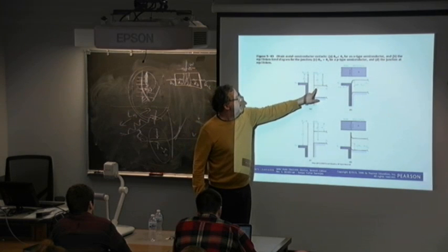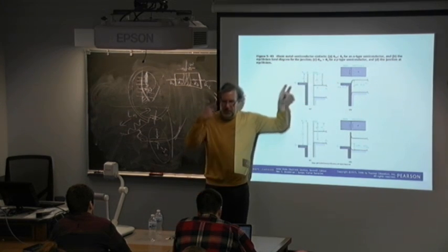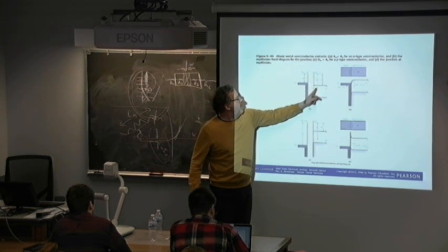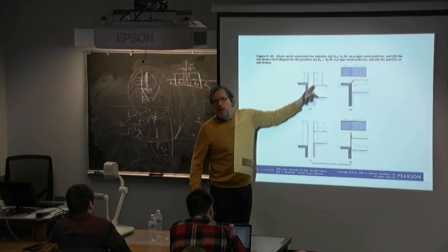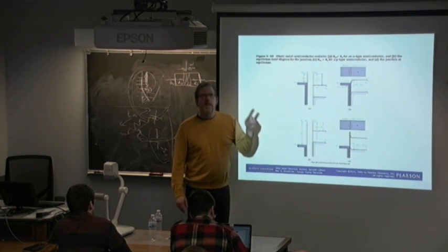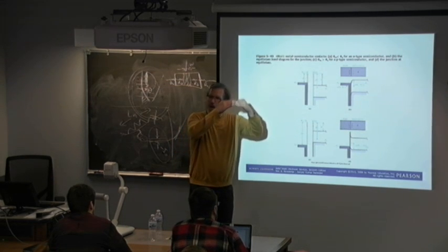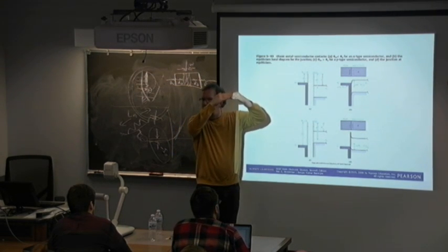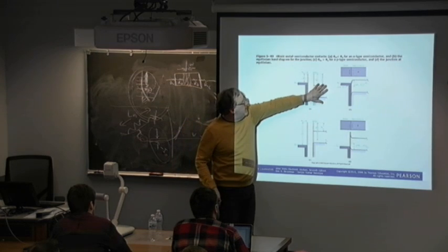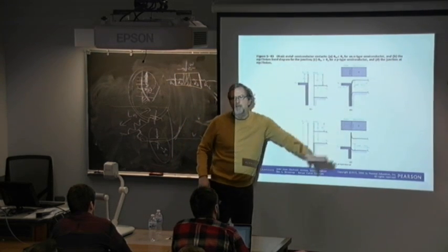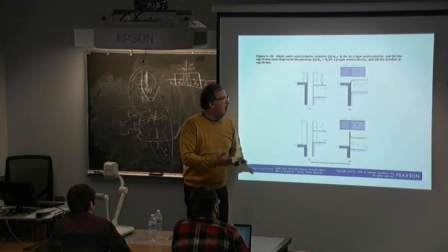How do I take a semiconductor up? Well, let's rationalize it. To put a Fermi level in a semiconductor higher means that the surface is becoming electron rich, right? To go up means it's becoming more full of electrons, and it's an N-type material. So how does an N-type material become more full of electrons?